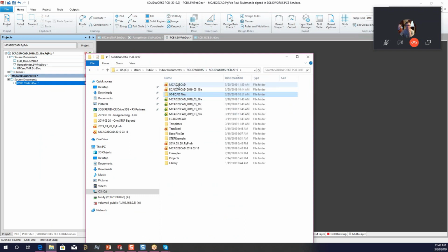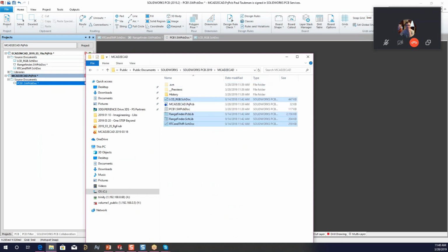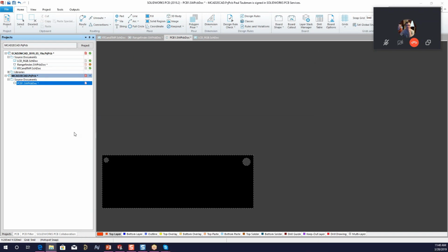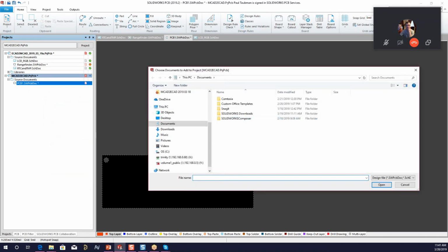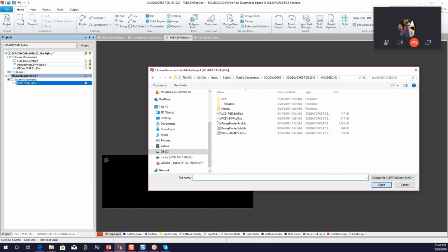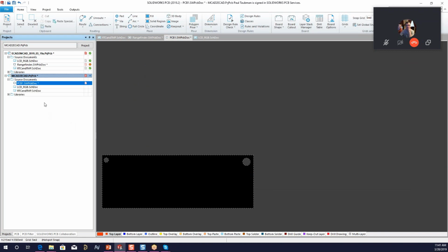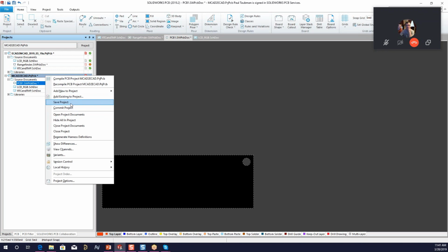I'm going to copy these into this new project that just got created, and put those in there. However, I've also got to tell this thing called the PRJ PCB that these are associated with it. So I'll do add existing to it. Let me just grab this directory here. I wish we could do a Julia Child on this, where it just instantly shows up, but it doesn't work that way. So bear with me as we pull these things together. Hopefully you see what's going on here. We just have to get those things synced up. So I'm going to bring in my 2 schematics and then again my libraries, and I'll press open here. And those are now associated with this project.